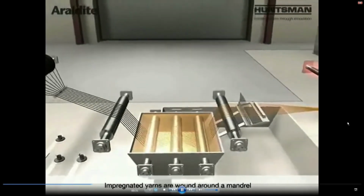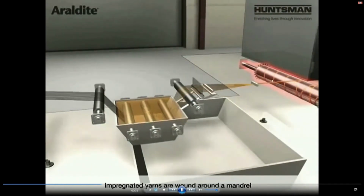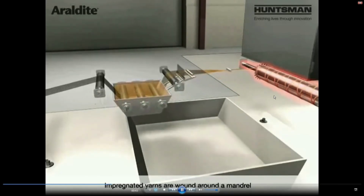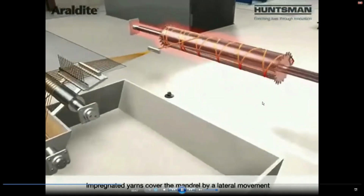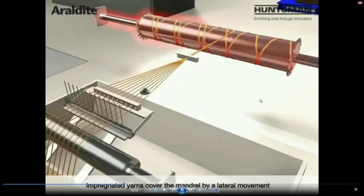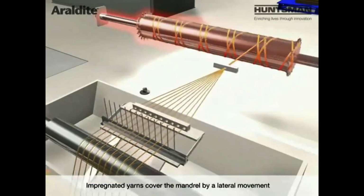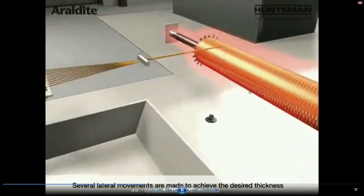on the rotating mandrel. This is a movement of the fibers and this is the rotating mandrel, and the impregnated fibers are getting wound over the rotating mandrel. The red color signifies that the mandrel is hot in order to ensure the curing process. The impregnated yarns cover the mandrel by a lateral movement. This is a lateral movement of the carriage being shown.